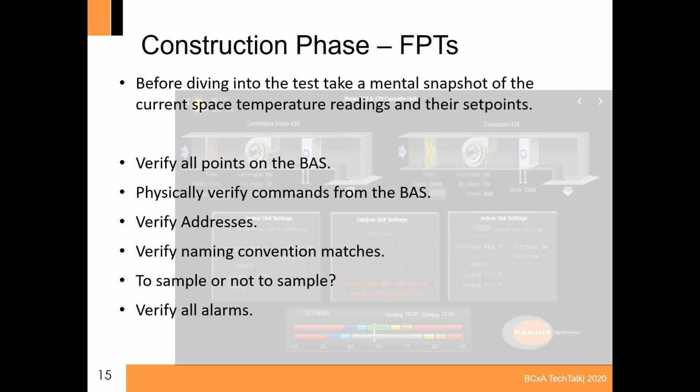So then we quickly went through and reset up the thermostats so that the unit would control off of space temperature instead of its return temperature, and that addressed the issue.